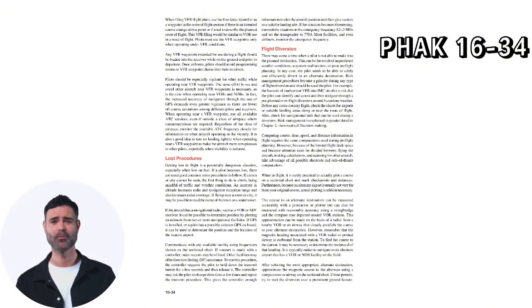Pilots should be especially vigilant for other traffic while operating near VFR waypoints. The same effort to see and avoid other aircraft near VFR waypoints is necessary, as is the case when operating near VORs and NDBs. In fact, the increased accuracy of navigation through the use of GPS demands even greater vigilance as there are fewer off-course deviations among different pilots and receivers.